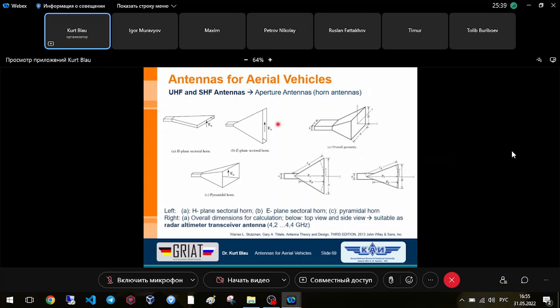And the radiation pattern looks like a sheet laying in this plane here, very small, and in this direction very small, and here it's very wide, and here is also the opposite, very wide. And now we can combine both antenna types in this pyramidal horn, and then we have a radiation diagram which is small enough in both directions.